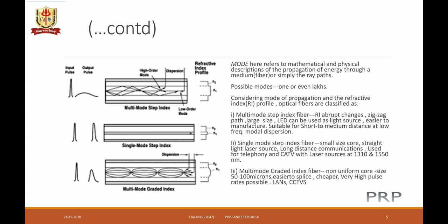Long distance communication will take place using single mode step index with lesser loss and high data rate, and it is used for telephony and CATV with laser sources at 1310 nanometer and 1550 nanometer of light wavelength.